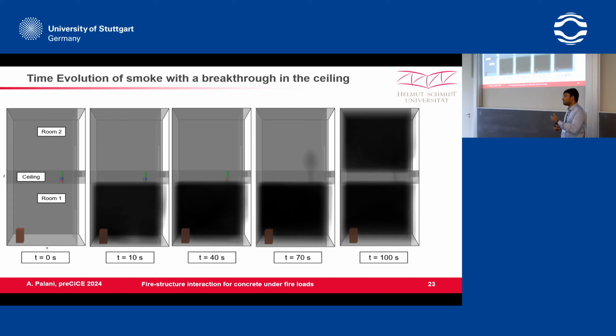He takes the array and applies it as a boundary condition to the structural solver, and that is causing a lot of problems. So at the moment we only pass the surface, and we are not worried about the newly created cells. Even though I am removing it from the fire solver, we still have the position, and that position is still computing the surface temperature of the solid wall and sending that temperature to the structural solver.